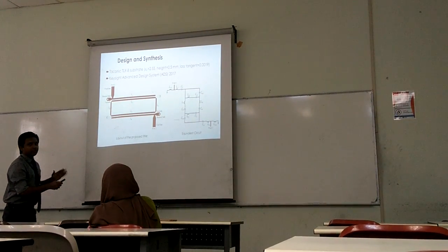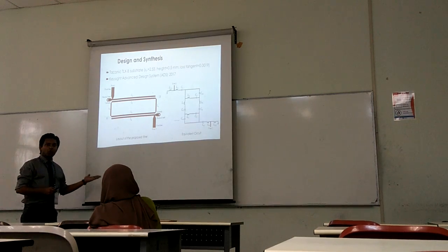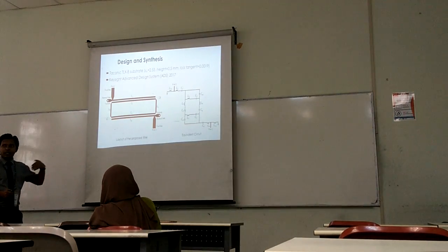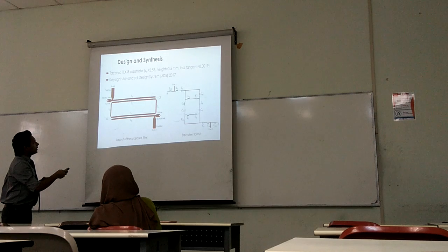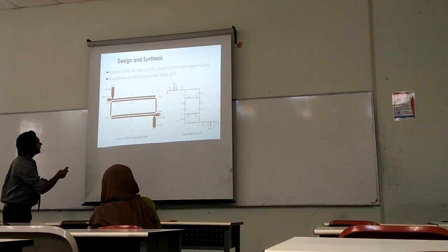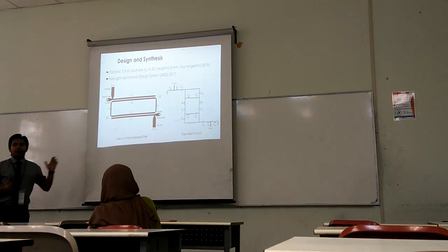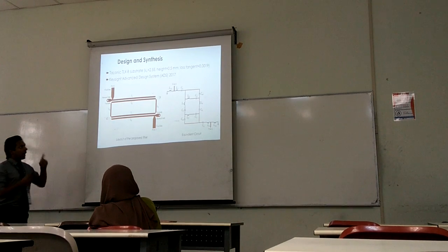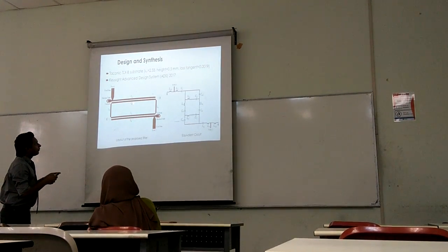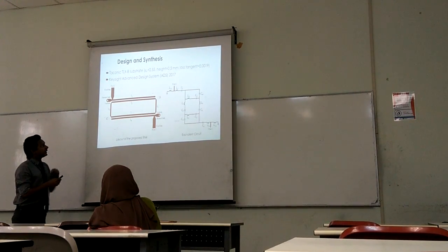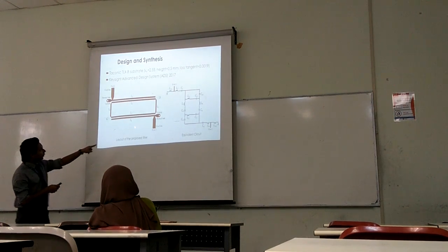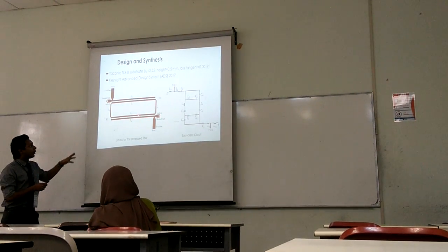And if you increase the length, just the opposite: the frequency goes below 2.4 gigahertz, to the lower frequency. And L6 and L5 determine the bandwidth. So for our design, we have considered these three things. All these three things we are finding from this proposed design layout.